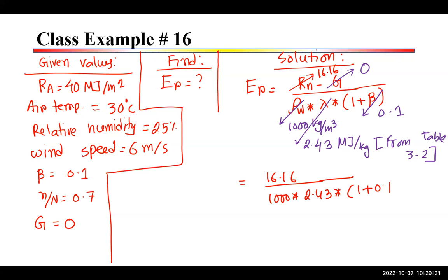One plus 0.1. I think you will get 0.006 meter per day, right? Since it's the daily evaporation. Now, 0.006, it's not hard to imagine what the length will be. So what you can do, you can multiply that by 1,000 and you get 6 millimeter per day. All of you have that one?